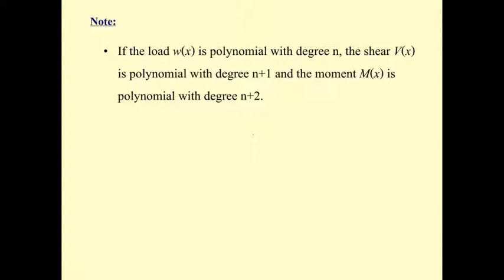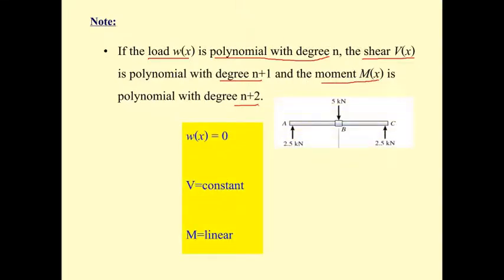Go back to the previous clip and try to remember the 3 examples, and we can get a conclusion that if the distributed load is polynomial with degree n, the shear force will have the degree of n plus 1, and the moment is going to have the degree of n plus 2. Okay, let's recall our previous example.